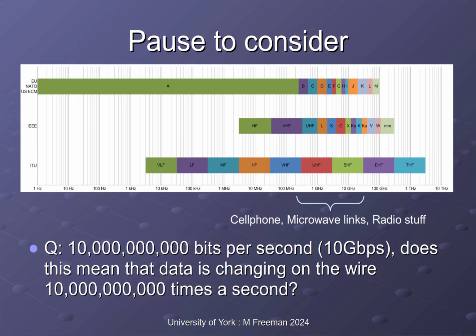Alternatively, you can avoid all of these problems associated with resistance, inductance and capacitance by going to fibre. If you go to fibre optic cables, obviously you're transmitting your data now as pulses of light, so all of those issues are removed, and that's what you tend to see. So if you're going for longer cable runs, kilometers worth of cable, then that'll be fibre.